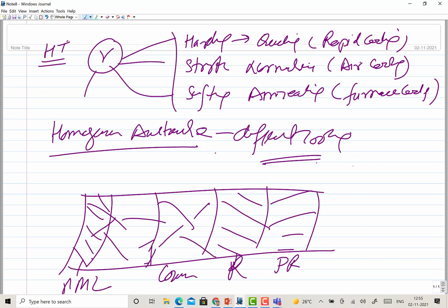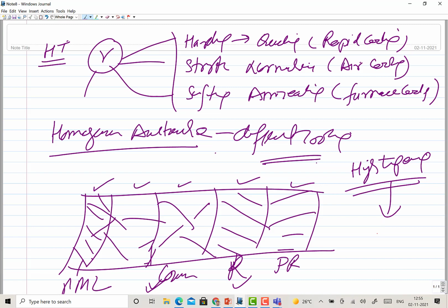Now when you give the high temperature exposure for solutionizing purpose, all these being of different constituents and of different sizes, they will respond differently. Something which is fine will respond differently than something which is very coarse. Thereafter, when you give one type of cooling rate, certainly you cannot give different cooling rates for the different zones during the post weld heat treatment. So you will give one type of heat treatment, and in that case each zone is going to respond in different ways.